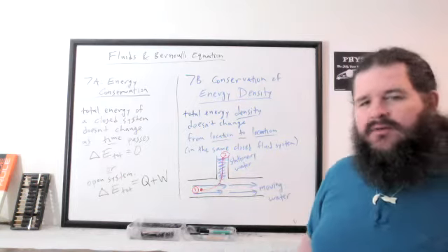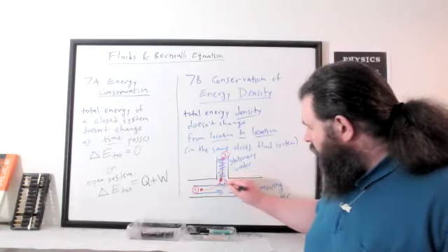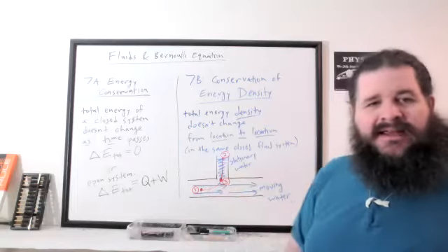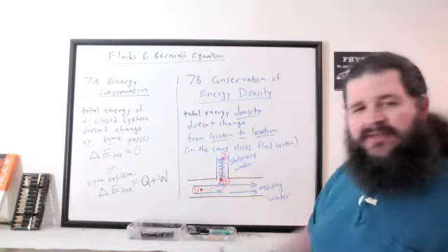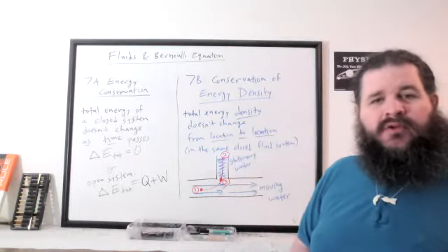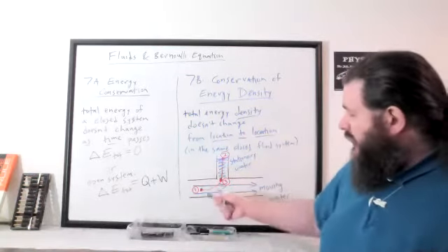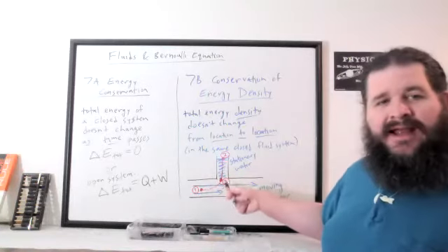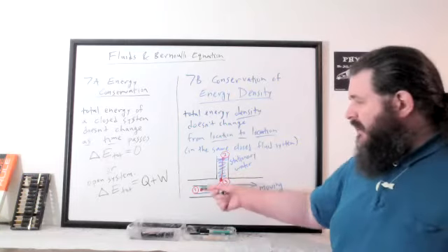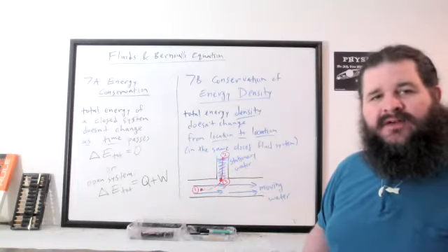So in a situation like that, usually what you want to do is introduce a new location. Let's call this point at the border point 3. If you're going from 1 to 3, that path is entirely in moving water. So 1 and 3 can be considered part of the same fluid system. If you go from 3 to 2, you're going only through stationary water. So 3 and 2 can be considered part of the same fluid system, which means you can run a Bernoulli equation analysis on the 1 to 3 change and separately run a Bernoulli equation analysis on the 3 to 2 change. So you can indirectly link points 1 and 2 together by comparing them both to this in-between point 3. And this is often a very useful approach.